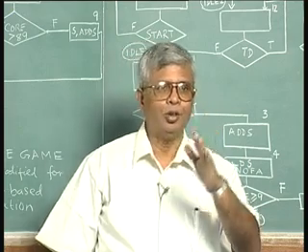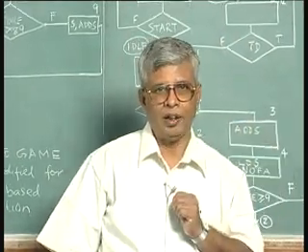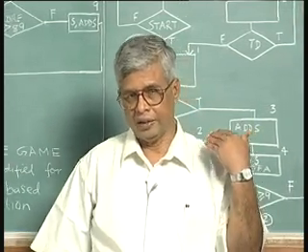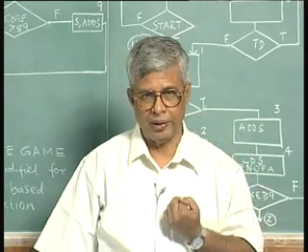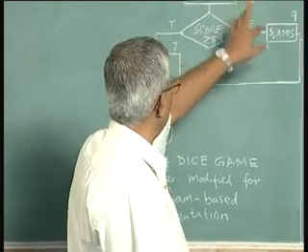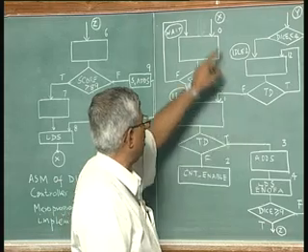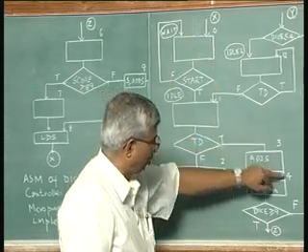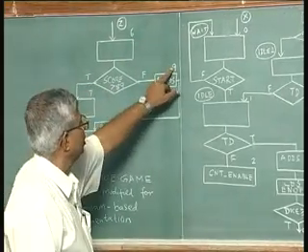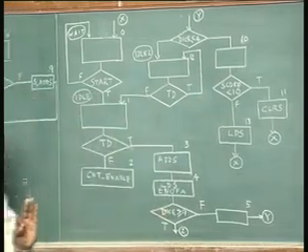So, it is not going to be an enormous increase in size, whereas the number of qualifiers, which affects the size of the ROM exponentially, is now going to save us, giving a reduced ROM size that we require in this case. Now, with these values of state variables, state addresses start from 0, 1, 2, 3, 4, 5, 6, 7, 8, 9, 10, 11, 12, 13, a total of 14 states.